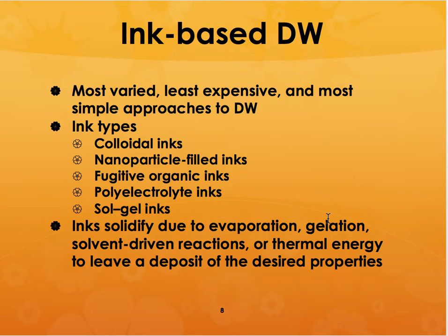Okay, so inkjet based technologies, direct write technologies, are the least expensive and most simple approaches. Many of these technologies have been able to take the inkjet printing approach and modify that to do direct writing. And for that, you need to have many different kinds of ink types.